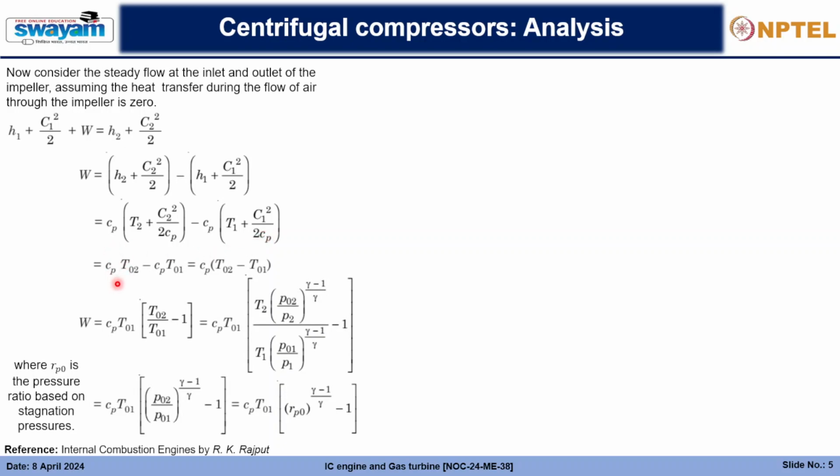Accordingly, we'll find that work done is equal to Cp into T02, that is the stagnation temperature out here, the absolute temperatures, and from here we will go into thermodynamic analysis such that we will take common T02 and we will have a ratio of T02 by T01.